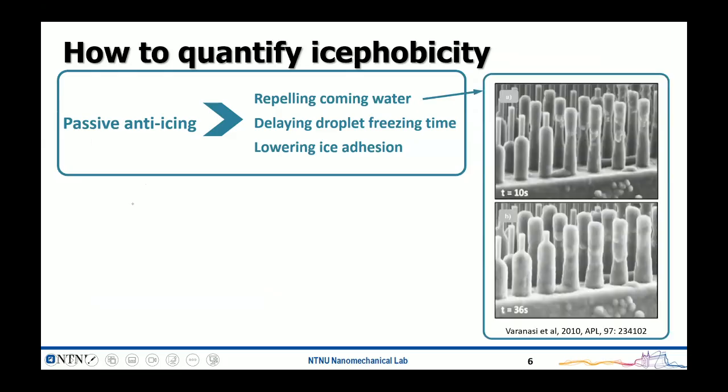So we see here, if the first one, the surface should always repel the incoming water, then it's just this superhydrophobic surface with super high contact angle, and with any tilting or impact to the surface, a water droplet will slide down automatically. However, researchers have shown that even in a very short time, in a high vapor pressure case, tiny water droplets will just condense in the pockets of those surface structures, and then form ice at an even lower temperature. So superhydrophobicity doesn't really work for ice phobicity.